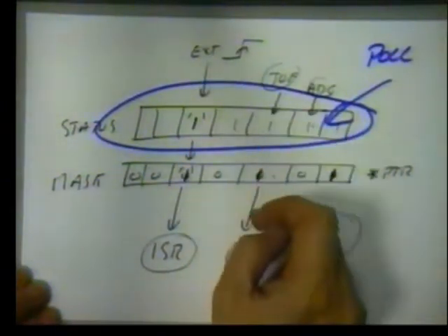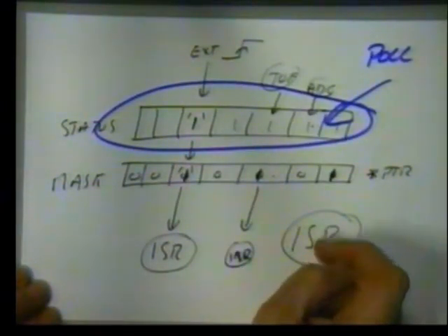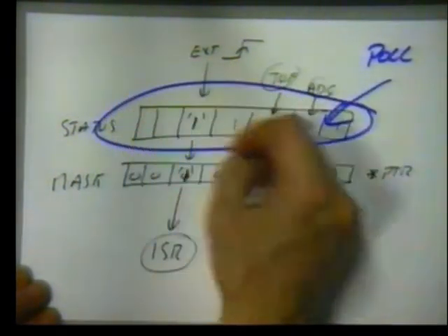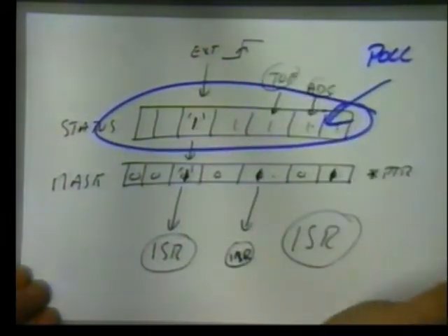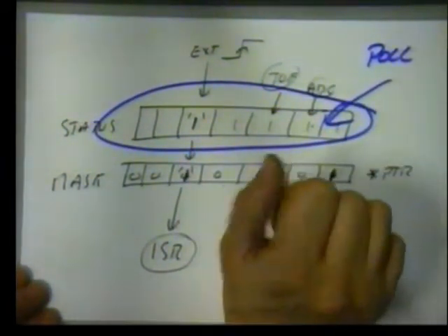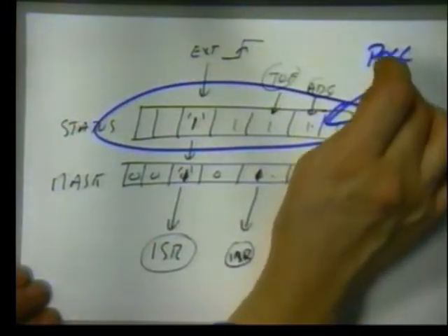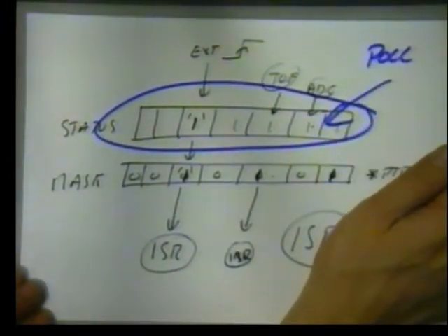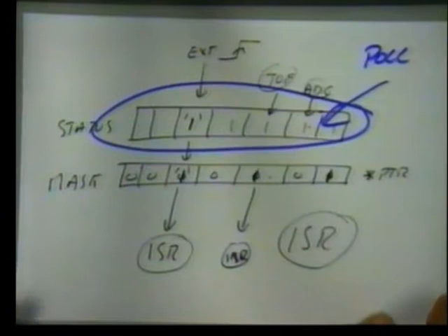You can either use the interrupt mask to allow them to issue the interrupt service routine, or you can simply poll the contents of the status register in your program and execute those programs whenever you want in a more structured manner with a much simpler memory data handling structure. So there are the two options for interrupt handling. Either you can let the ISRs occur, or you can poll them through the interrupt status register.